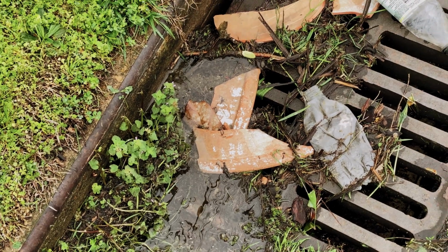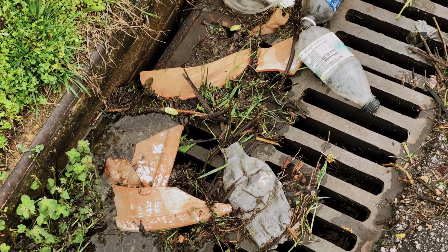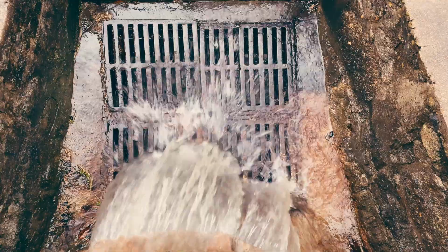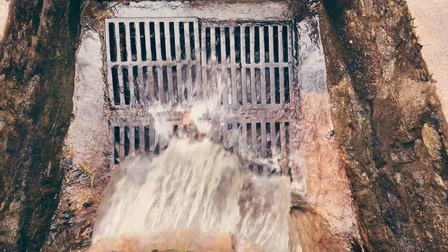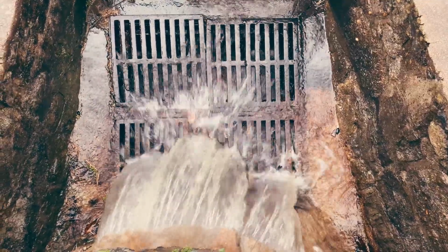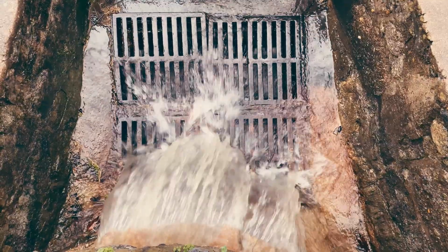Many drainage and sewer systems fail for one simple reason: the pipe slope was wrong. When it's too flat, the water stagnates. At the same time, when it's too steep, the solids get left behind. Poor slope design always leads to blocked sewers, overflowing drains, and expensive repairs.